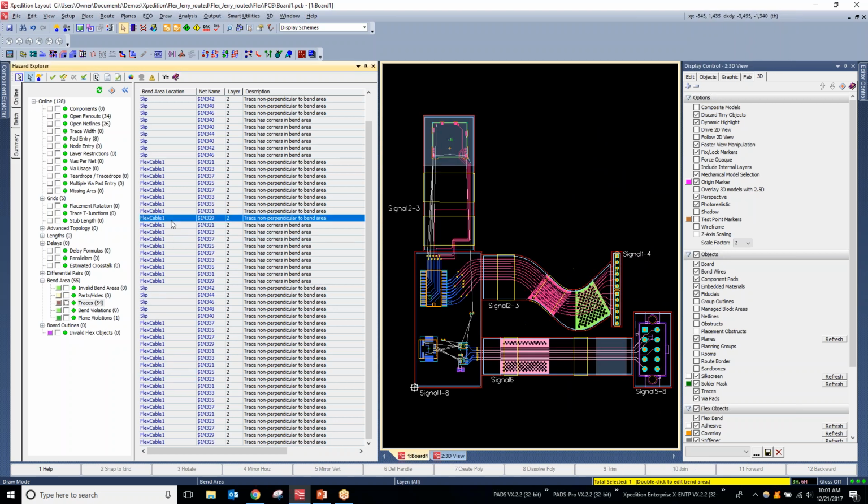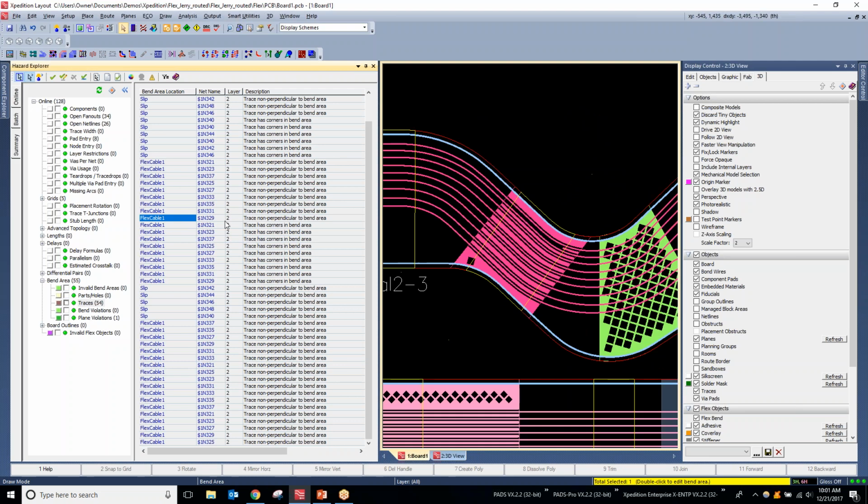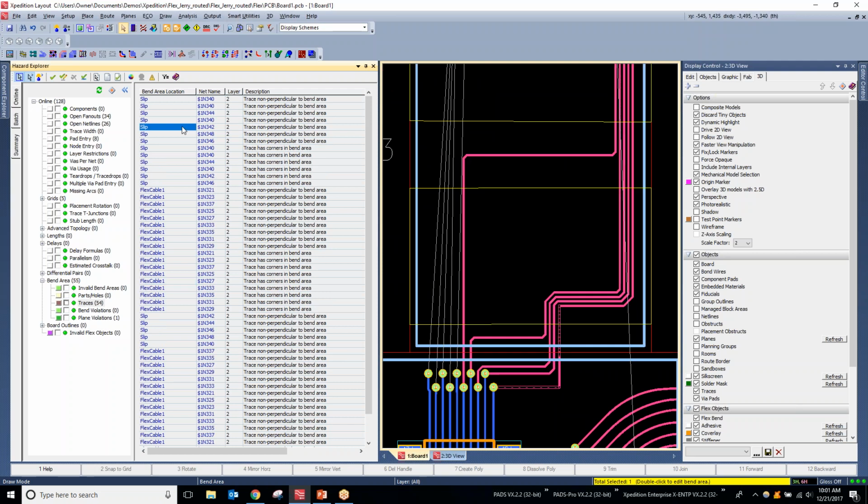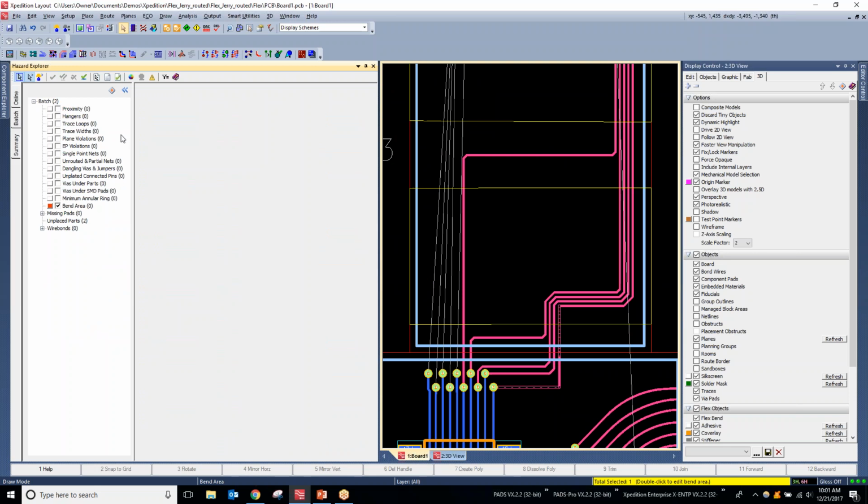Okay. So it'll come in and highlight it for us and allow us to understand where that DRC rule is and how to fix that a little bit easier. Okay, so this is an online DRC, what we can do. And then also we do have the ability to run a batch DRC and output a text document or report just to see those types of batch DRC violations.